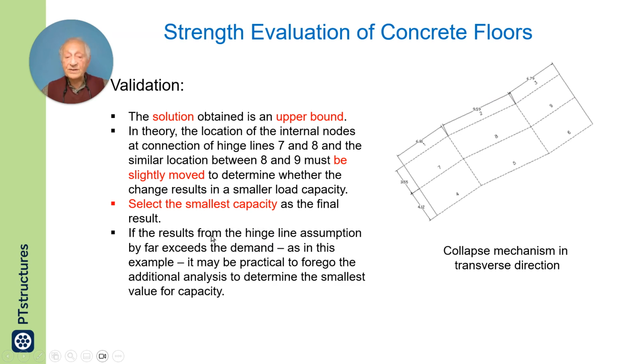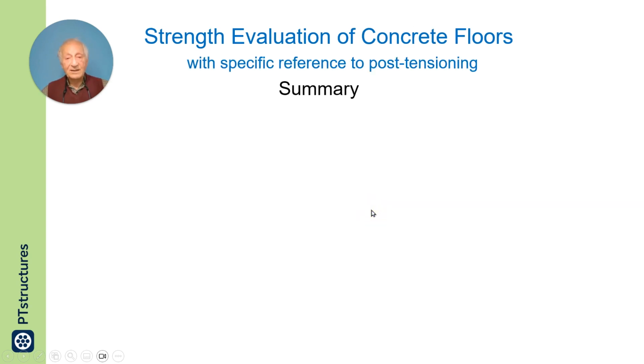But the results from the hinge lines assumed by far exceeded the demand. As in this example, it may be practical to forego the additional analysis to determine the smallest value for capacity. It was considered that by moving these nodes a little bit around, the answer will be different, but the difference will not invalidate the conclusion.